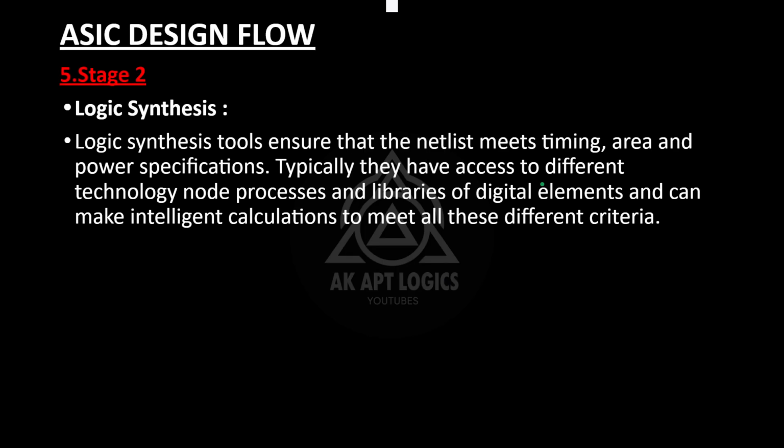Then the logical synthesis tool ensures that the netlist meets timing, area, and power specifications. It means it also checks that the design code matches the timing, area, and power specifications which are given by the user in the beginning.